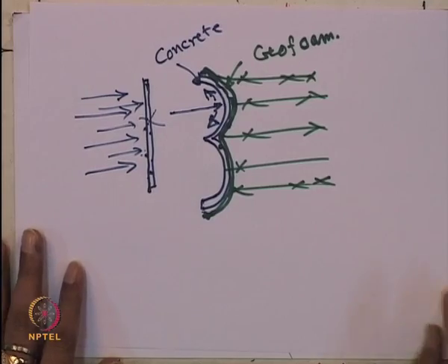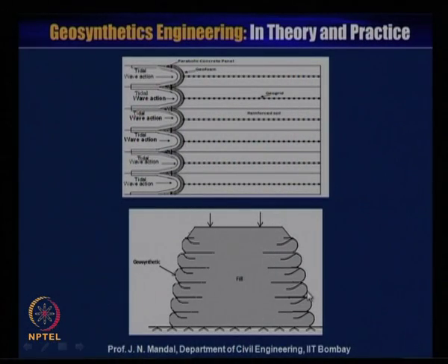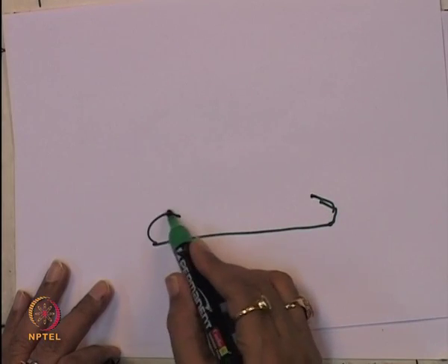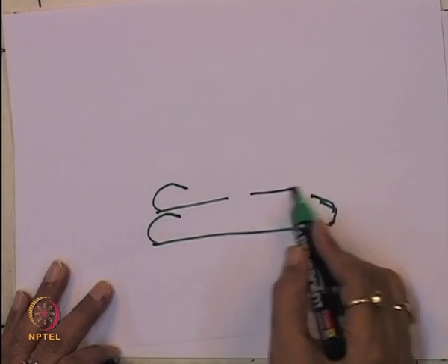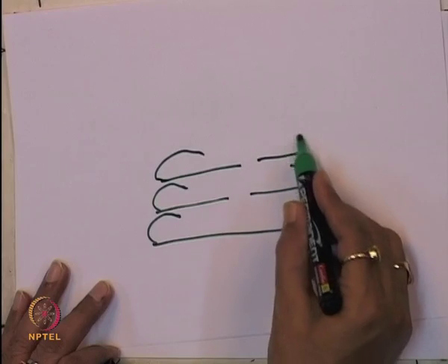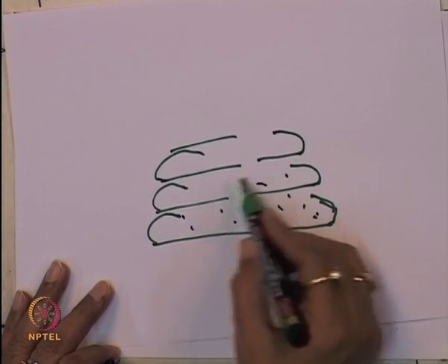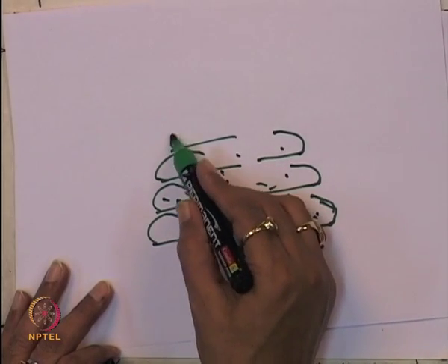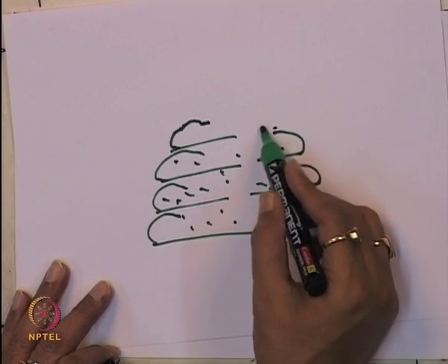Most of the time, when the tsunami comes and people run away, they don't know where to go, where to run, where to stay. So you can construct this kind of structure near the seashore, and it is very simple. You can place normal geotextile material and wrap it like this, then make another layer like this. So you can construct any height like this, and it is filled with local sea material, you can fill it up with sand, like a wrapping system